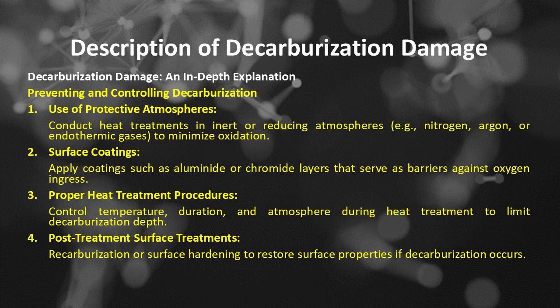Number 3. Proper heat treatment procedures. Control temperature, duration, and atmosphere during heat treatment to limit decarburization depth. Number 4. Post-treatment surface treatments, recarburization or surface hardening to restore surface properties if decarburization occurs.